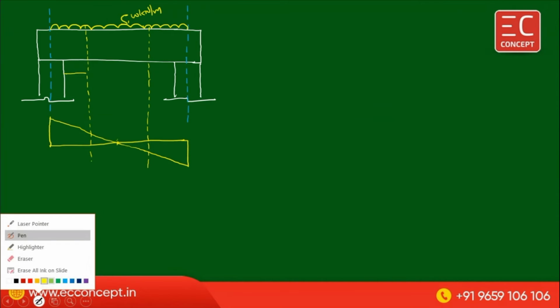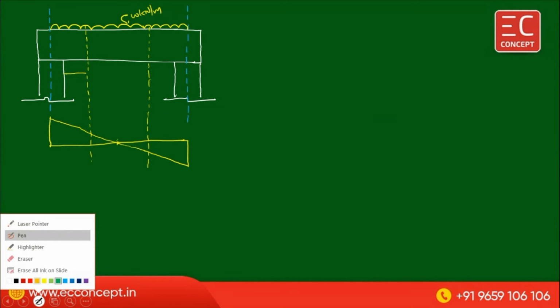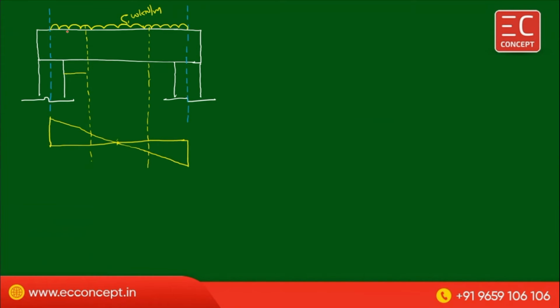What it says is you have to use stirrups up to this critical section. The stirrups shall be used closely up to the critical section, and from here itself also the stirrups shall be used very closely, where the shear force is maximum.